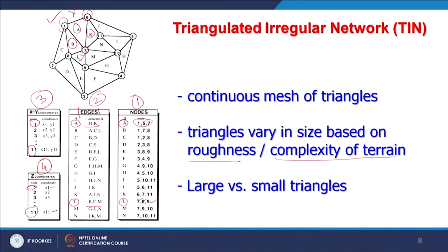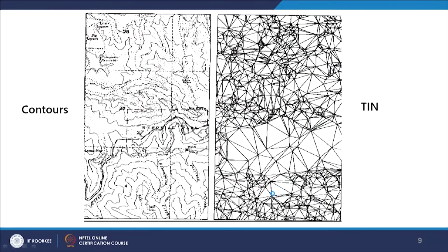be formed. However, mass points may have the same density as in the case of the Himalaya, but still larger triangles will be formed because the relief roughness is not there; the terrain is not complex from a topographic point of view. So, this is adaptable. This is done depending on your input mass points and terrain roughness. So, one has to remember this, and therefore the small and large triangles keep on going.